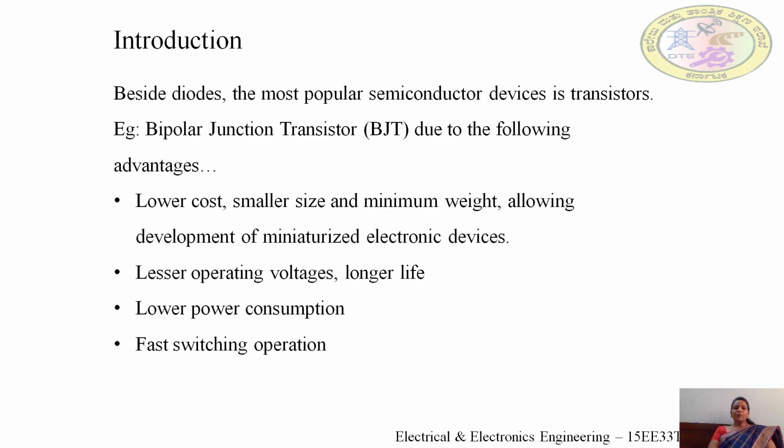When a trivalent impurity is added to a pure semiconducting material, the resulting material is a p-type material. And what do you mean by a trivalent impurity? Trivalent impurities are those having 3 valence electrons. Similarly, when a pentavalent material having 5 valence electrons is added to a pure semiconducting material, the resulting material is an n-type material. P-type materials have holes as majority charge carriers, whereas n-type materials have electrons as their majority charge carriers.